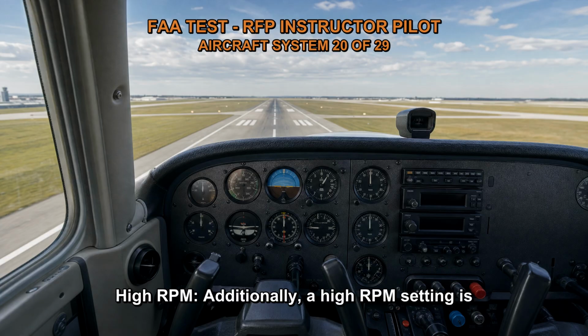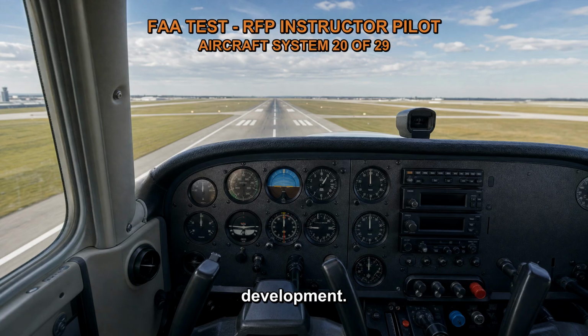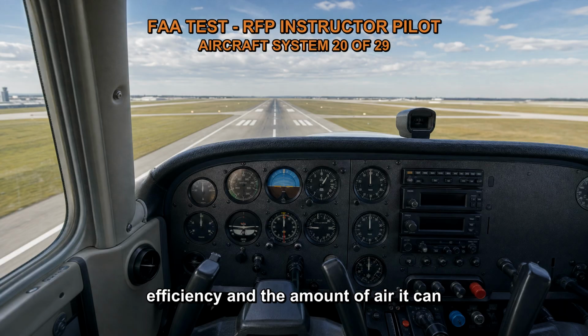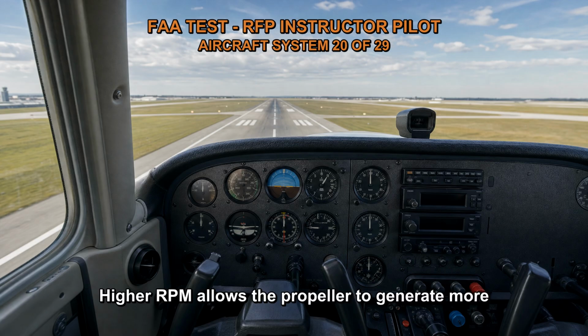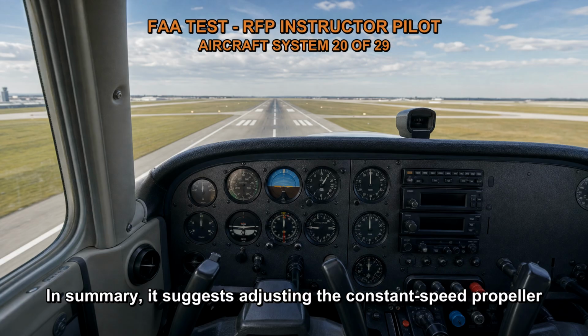High RPM. Additionally, a high RPM setting is required to achieve maximum power absorption and thrust development. The rotational speed of the propeller affects its efficiency and the amount of air it can move per unit of time. Higher RPM allows the propeller to generate more thrust by moving a larger mass of air at a faster rate.